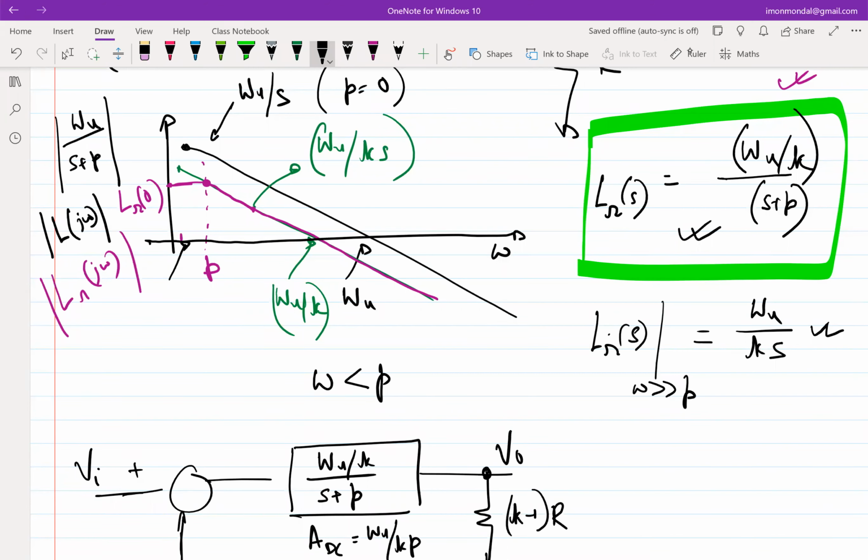Sorry, my choice of words was not correct, so let me rephrase. If you have an ideal integrator and a DC input, it cannot sustain a finite input error voltage, because with a finite input error voltage the integrator has infinite gain and will keep ramping. But now the integrator doesn't have infinite gain, which means there is a solution where the integrator can sustain a finite input voltage.